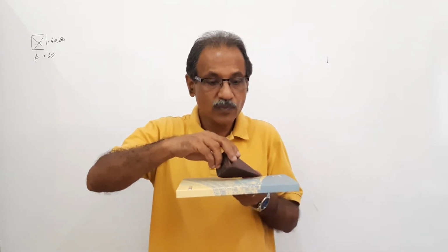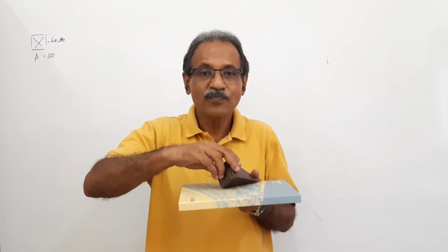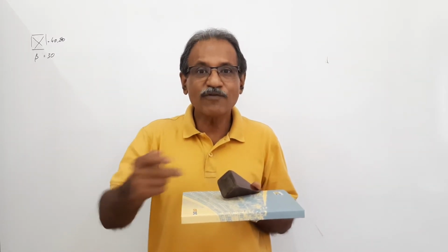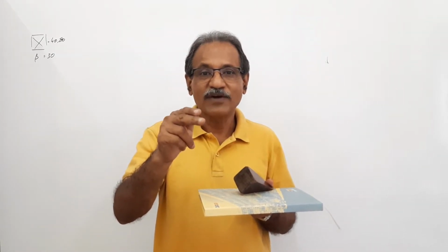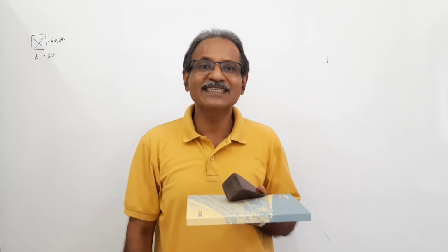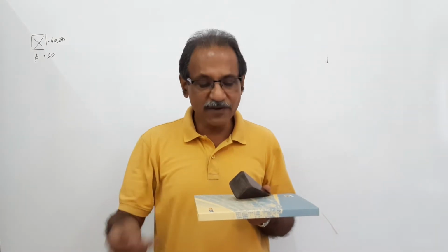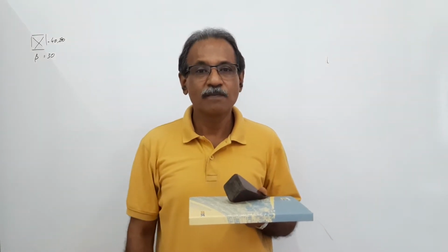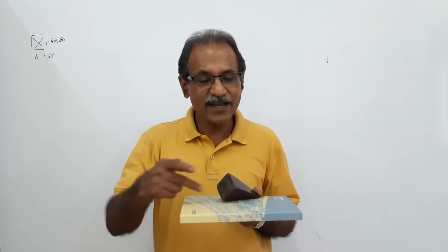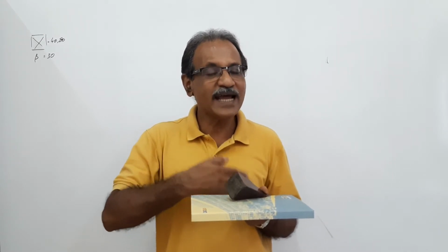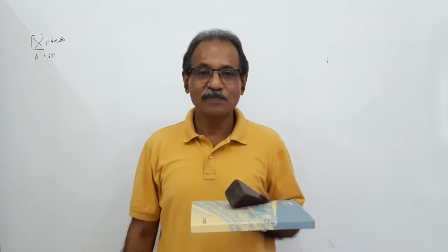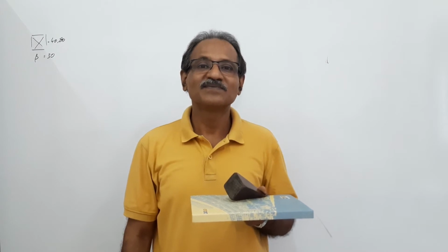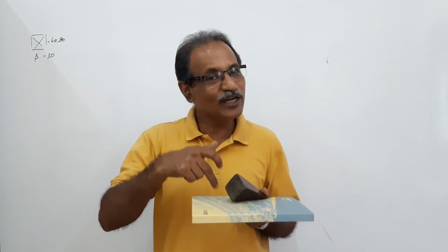Now, listen carefully. Beta of axis is 30. What is phi of axis? Phi of axis is less than 30. We don't know how much it is. Now, tell me the angle between the slant edge and VP. It is lying on a slant edge now. What is the angle between the slant edge and VP now? The angle between slant edge and VP is 30 itself, since the slant edge is on HP.